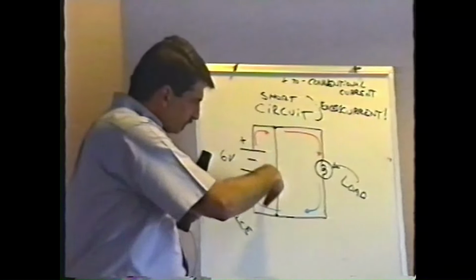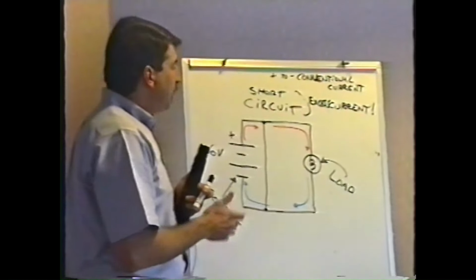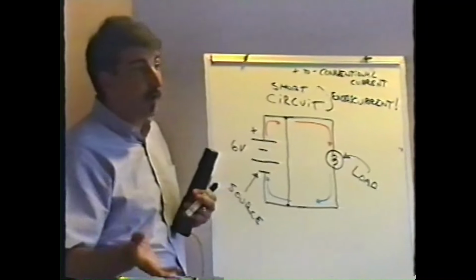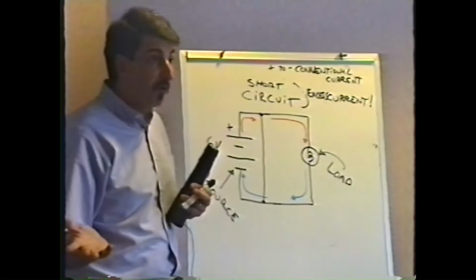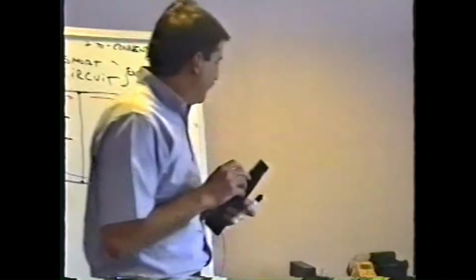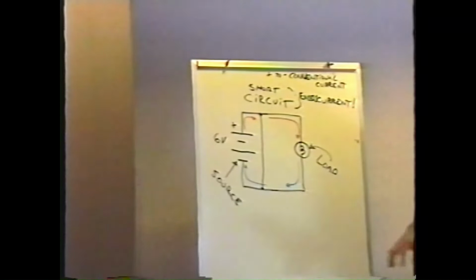There is nothing stopping the flow of electric current. With an open circuit, if you have a break in the wire somewhere or a break in the component, no electric current goes through at all. That's an open. Everybody with me so far? Okay? Pretty simple, right? But a lot of people make that mistake. They say anything that's bad is shorted, and that's not necessarily true.